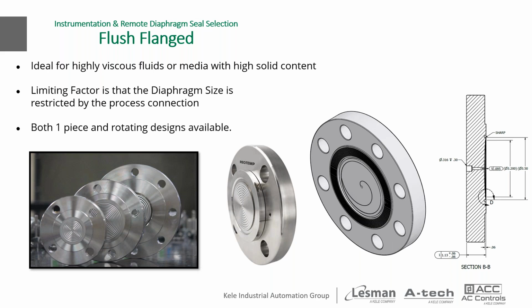Tom, we have a question. When you mentioned 2-inch, 3-inch, and 4-inch, are you referring to the diameter of the seal itself, or is that the flange process connection? Yeah, great question. I did say, and maybe we should type this in the future, it's 2-inch, 3-inch, and 4-inch ANSI 150 or 300. They are made in higher pressure classes, but yes, that is the pressure class of the seal. Did that answer the question? Yes, thank you. Yeah, no problem.